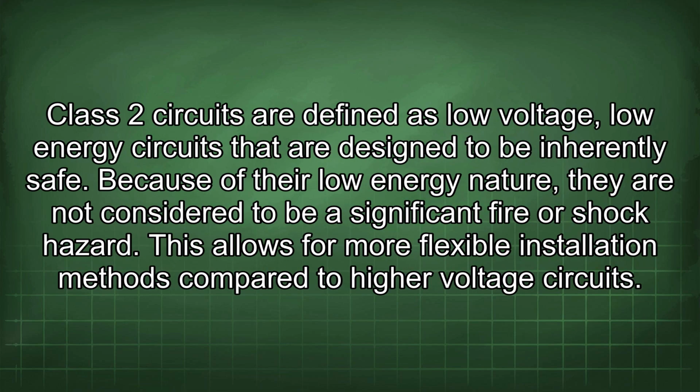Class 2 circuits are defined as low-voltage, low-energy circuits that are designed to be inherently safe. Because of their low-energy nature, they are not considered to be a significant fire or shock hazard. This allows for more flexible installation methods compared to higher voltage circuits.